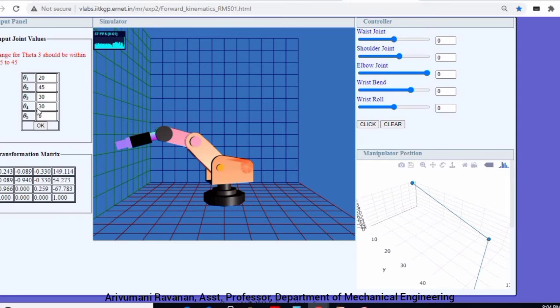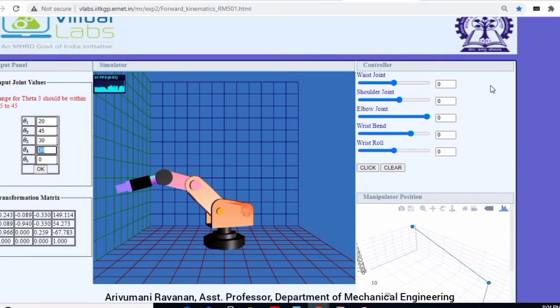But now we get into the next thing. The third one is about the controller. When you are discussing the controller, to see the individual movement of the links, drag the slider on the controller panel. The teaching box allows the user to manually move all the joints of the robot unit and store positions as desired. For instance, the waist joint, the range of this waist joint is up to 300 degrees,